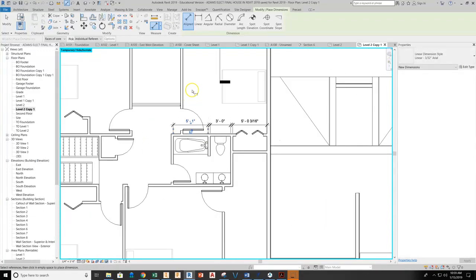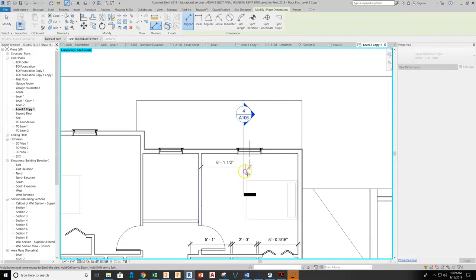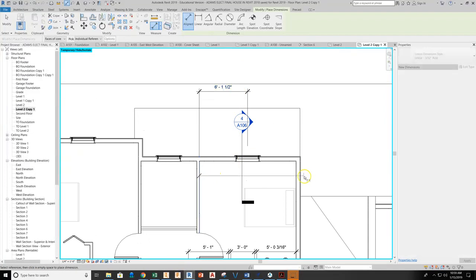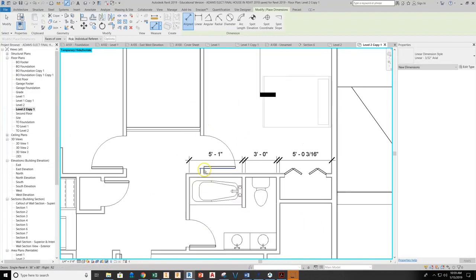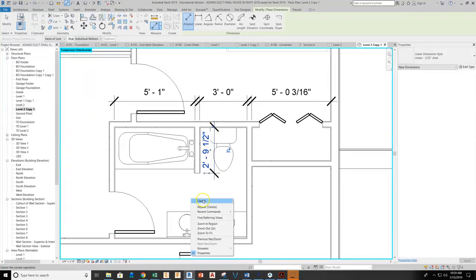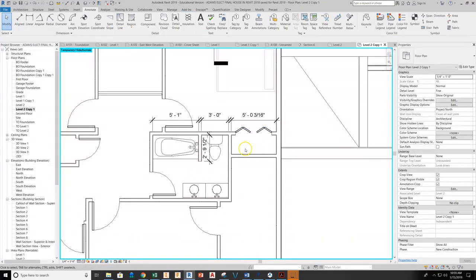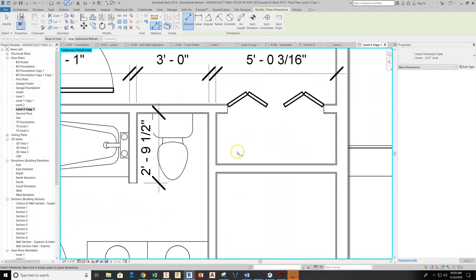This wall for the bedroom would actually get dimensioned here for the outside. We'd actually go to the window for this, and this would get pulled out, and then we'd end up having an overall for the room size. So it's not necessary to position that in this area, but would be necessary to give this proper information. May or may not be necessary to give the depth of this particular wall, but if you wanted to give that, you can give that in an area such as this to keep it nice and clean and neat. Again, it is as neat and clean as possible to lay out all of your drawings.